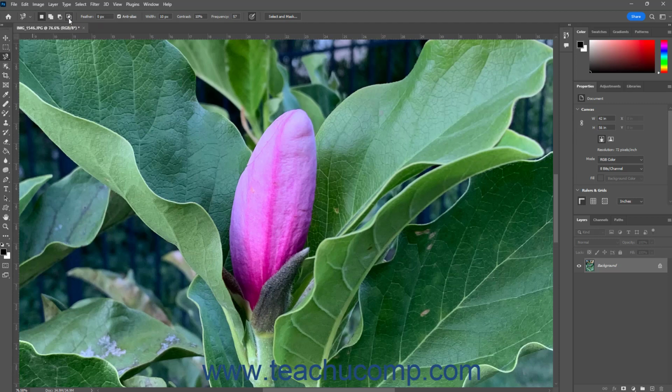This choice determines how the selection you are about to make interacts with any existing active selections in the Photoshop document. To apply feathering to your selection, which softens the selection border by changing the opacity or transparency of the pixels in its feathering border width, type the number of pixels of feathering width to apply to the selection border into the Feather field. To smooth rounded edges in the pixel selection, check the Anti-Alias checkbox.